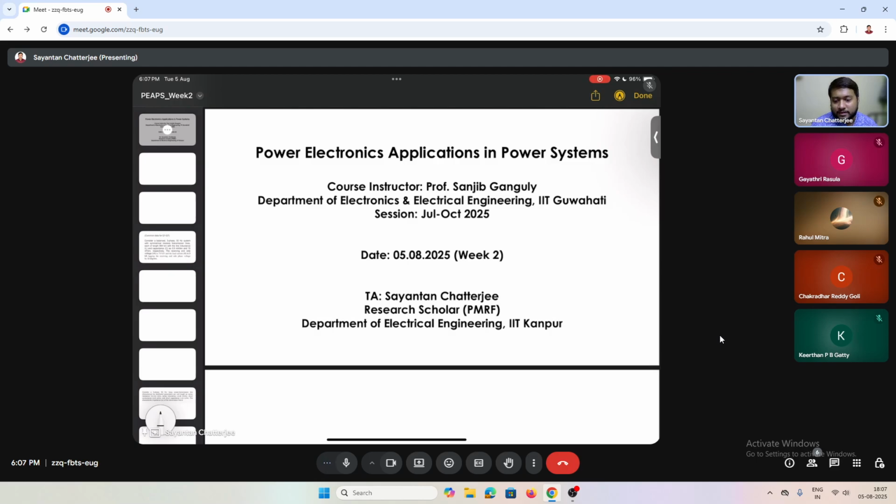So to get the right of way for these transmission lines, another thing is the cross arms. People are trying to work on the dielectrics part so that huge voltage levels can be transmitted, because the greater the distance of these cross arms, the more right of way is required.